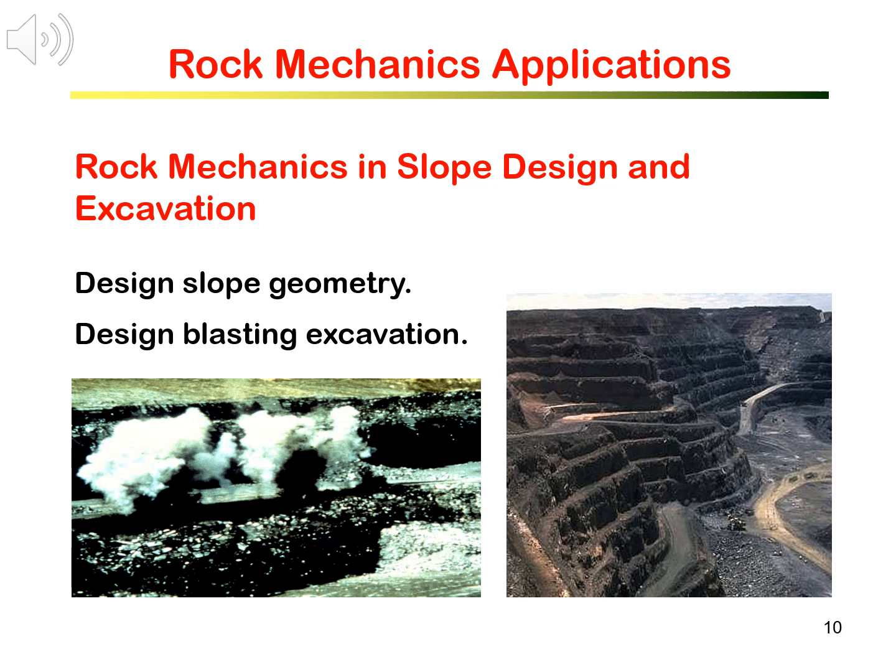Rock slopes are generally excavated by blasting using explosives. Blasting design for rock slope excavation requires knowledge of the interaction between blasting and rock strength, and the mechanics of rock fracturing and fragmentation under dynamic loading, to ensure the effectiveness of rock excavation as well as optimal slope stability.